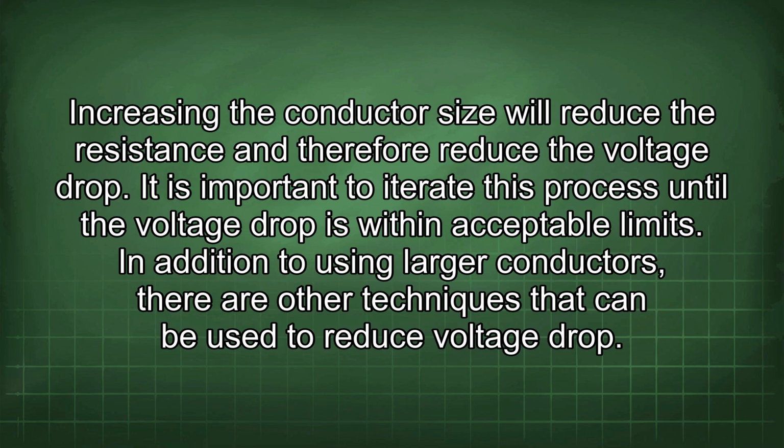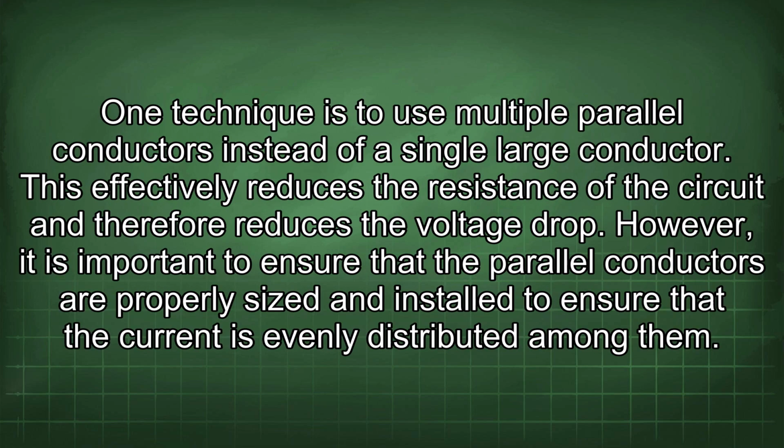In addition to using larger conductors, there are other techniques that can be used to reduce voltage drop. One technique is to use multiple parallel conductors instead of a single large conductor. This effectively reduces the resistance of the circuit and therefore reduces the voltage drop. However, it is important to ensure that the parallel conductors are properly sized and installed to ensure that the current is evenly distributed among them.